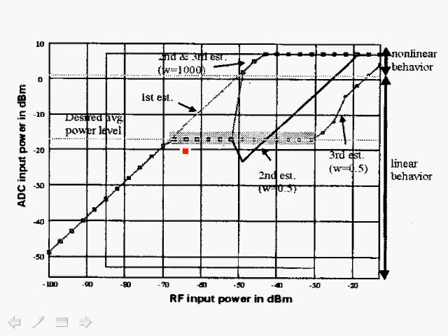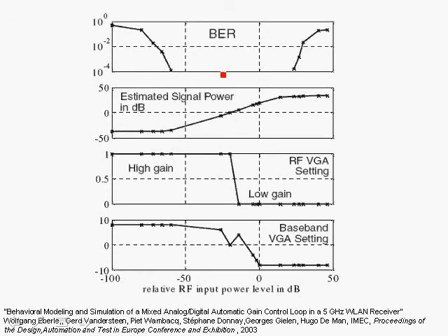The whole idea is to meet a target RMS value at the input of the A to D. Here we show 4 important curves that go a long way to explain how AGC works and how we can achieve a wide dynamic range using AGC, where the AGC control is in the baseband digital signal processor with interactions to the analog front end.